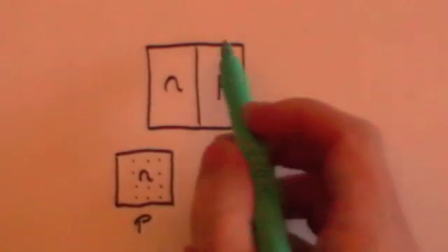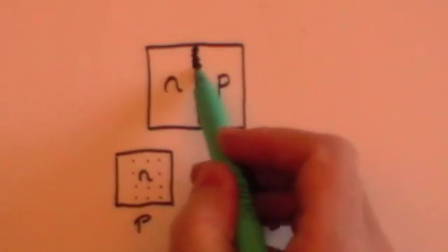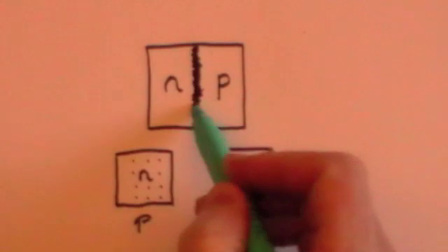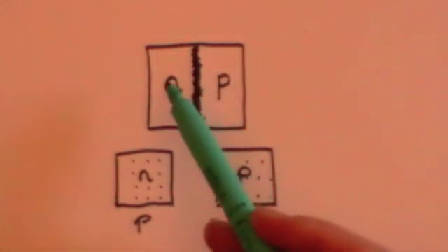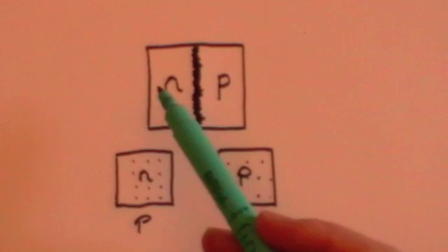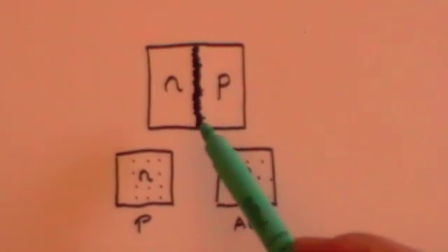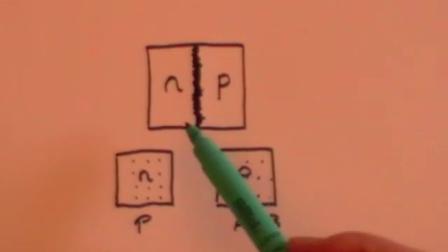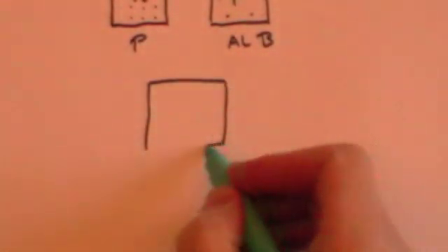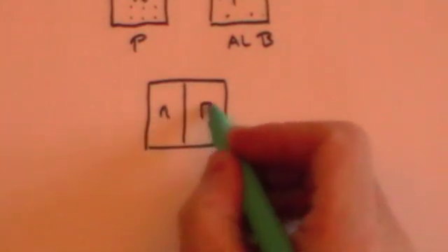And when you do that, I said you get what's called a depletion layer between the two. Because what effectively happens is that the net surplus of electrons balances the net deficit of electrons where they touch, to produce a depletion layer where there is effectively no free electrons. And then I said if you take this NP material, and you try to pass a current through it, and don't forget this is the depletion layer here, it depends which way you try to pass the current.